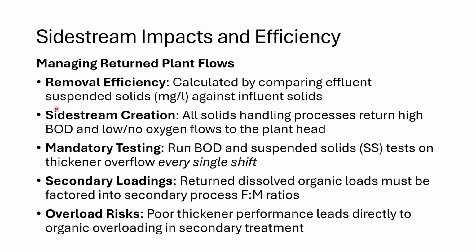You also have to look at a comparison. So I told you that BOD is the food, okay? That's the food microbe ratio here. BOD is the F part of the food microbe ratio. We're going to find out a little bit later, there's this thing called mixed liquor suspended solids, MLSS. MLSS is basically the microbes of your process. So BOD is the food, the microbes are the mixed liquor suspended solids.